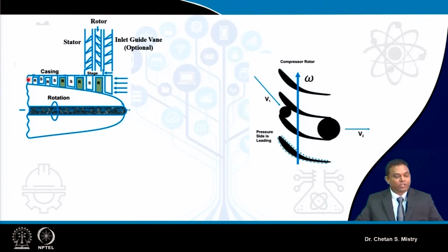Now this compressor comprises a number of stages, say 5 stages. From one stage to two to the third stage, going downstream, my pressure ratio is increasing. When pressure is increasing, from fundamentals you can realize my density is also increasing.